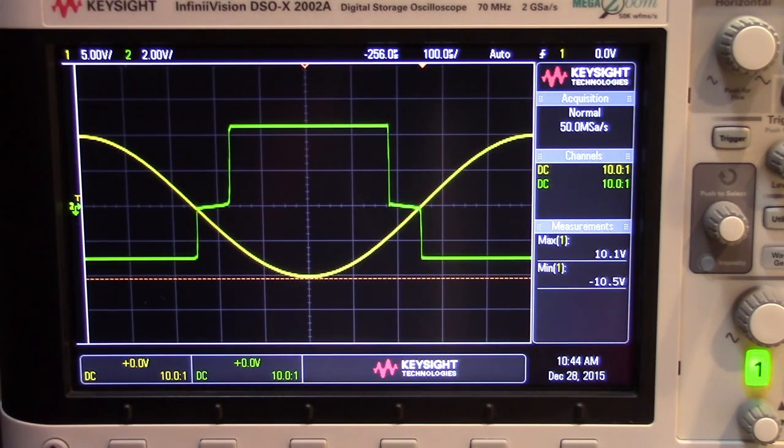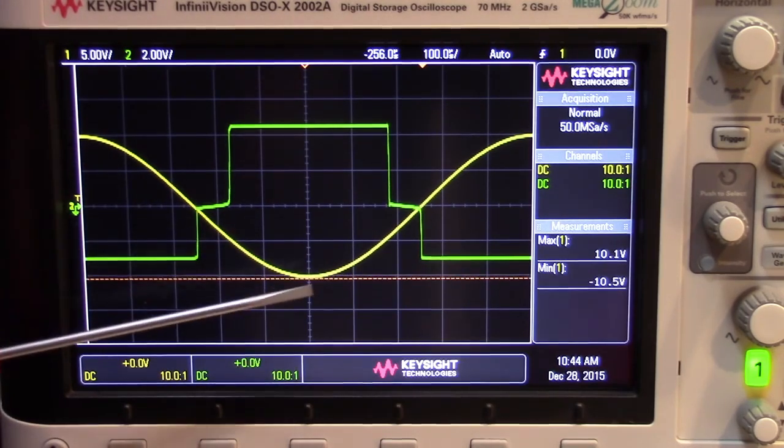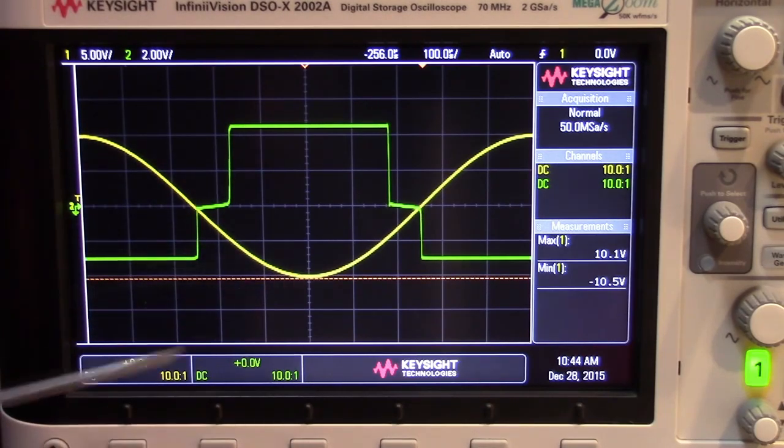And if we take a look at this on the scope, we can very clearly see what's going on. Again, I'm feeding a 20 volt peak-to-peak signal, plus 10 and minus 10 sine wave, into the Vin of the circuit. Again, my V plus voltage is 5 volts, and both of my resistors are of equal value. So once we count that D2 voltage drop, our negative trip voltage is going to be just a little above 5 volts at 4.4 volts.